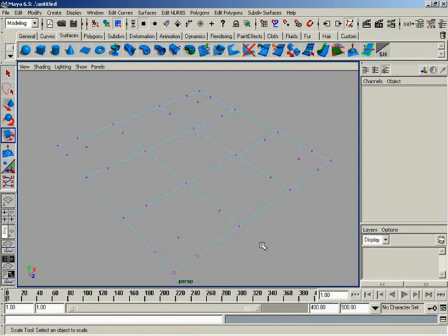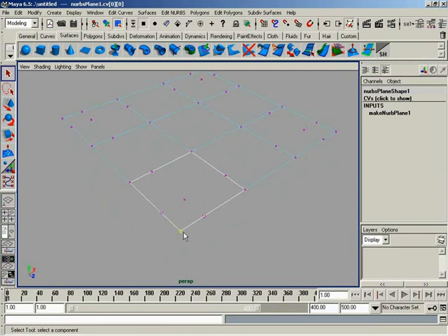Now, with the NURBS curve, you'll remember that the very first CV was an open box representing the starting location of the curve. Guess what? It's the exact same thing when dealing with a surface. So we've got an open box here, and this indicates the origin of our NURBS surface. And in a minute, I'm going to show you a display option that's available to quickly show you where a surface begins and which direction is U and V.